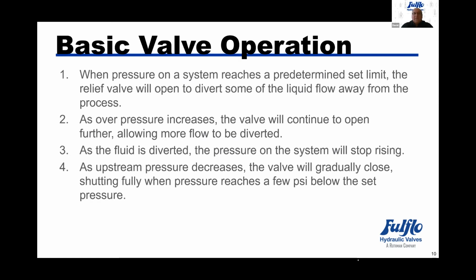The pressure stops rising, then the fluid is going to be diverted back to the tank until the valve would then be required to open or close at that point. As the upstream pressure decreases, the valve will gradually close back to the setting of the valve.